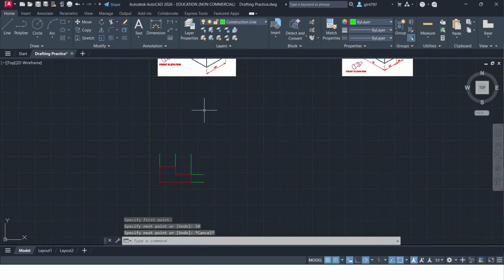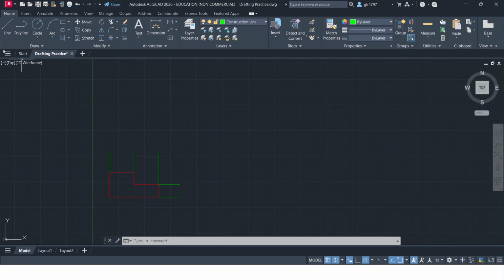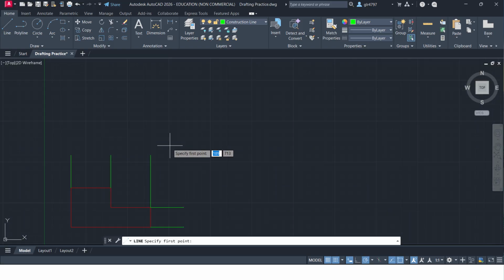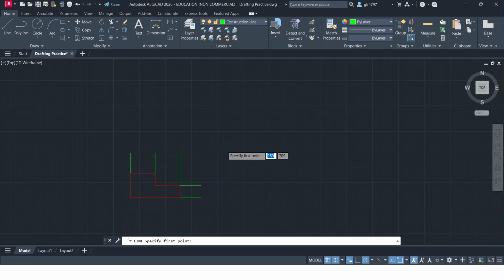All right. So one more thing we need to consider, and I'm going to introduce this new concept to you. It's called a reflection line. It allows you to take the geometry from the plan view and reflect it onto the right side view so you could capture everything more easily. How do we create this reflection line and how will it work? I will show you in one minute.